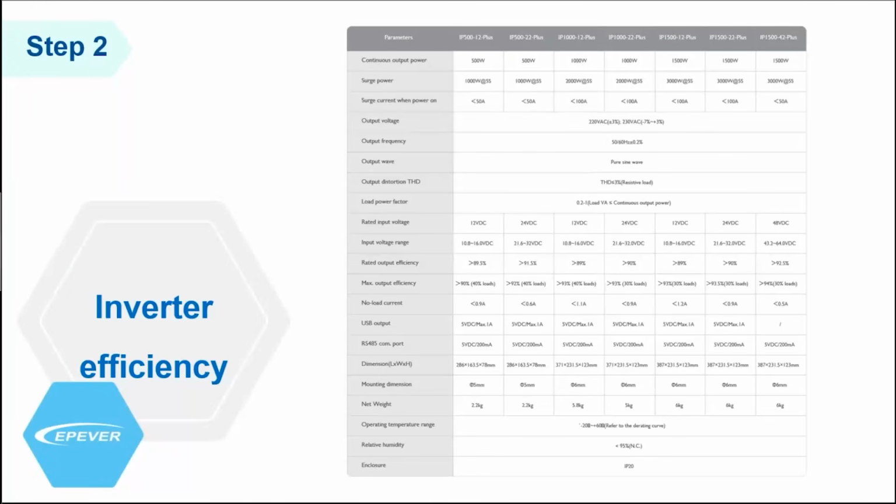We also talked about the inverter efficiency, and it's another term which affects the battery size. There is no ideal inverter, as I mentioned, and there is always a power loss in converting DC to AC. So this loss should be taken into account while calculating the power required for the batteries. There are lots of conversions happening in an inverter, like boosting the DC voltage to a high DC voltage, then a lot of switchings happening in the FET to convert the high DC to AC. And, well, there's a lot of loss.